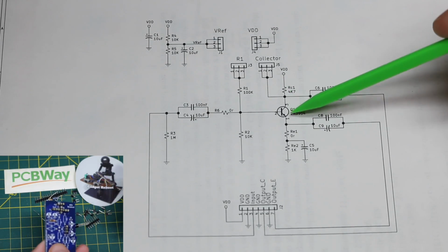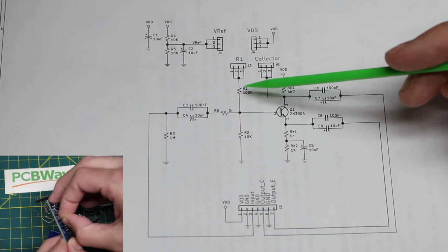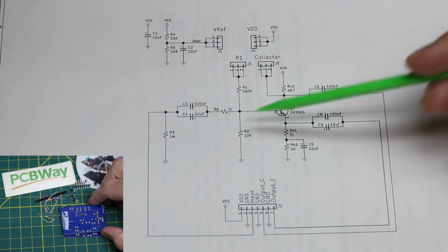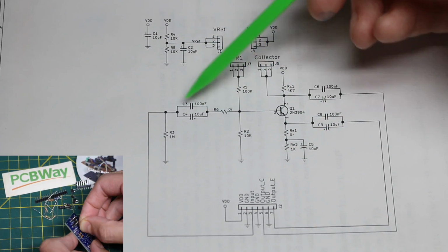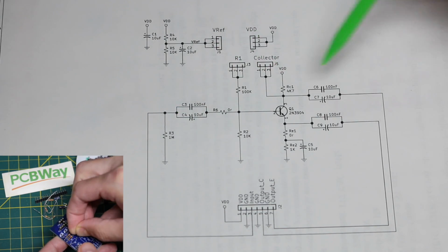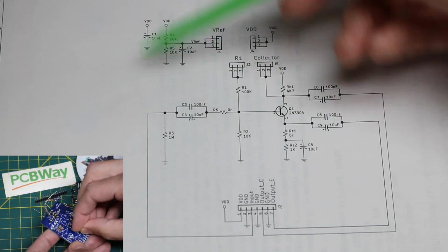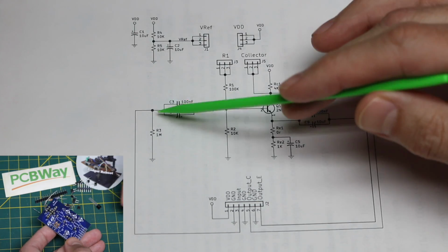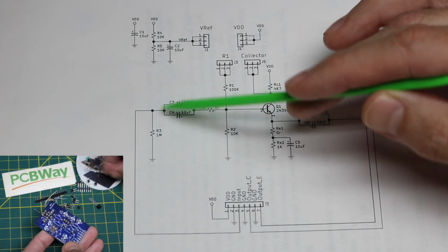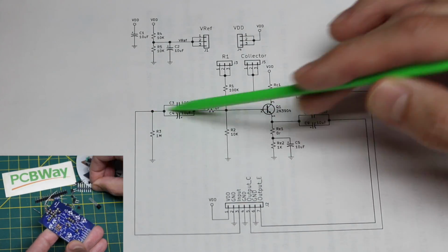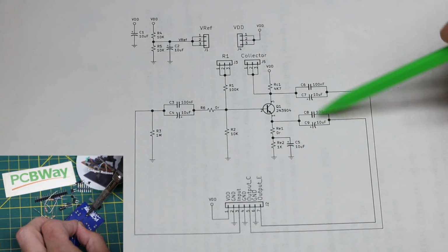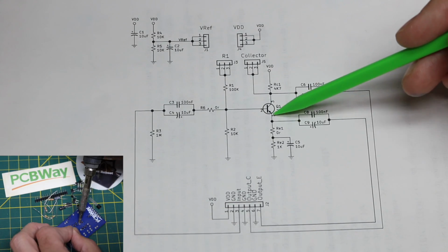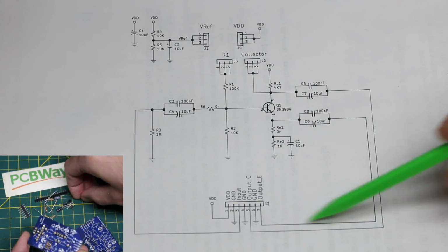So I have an NPN transistor, I have resistors for a voltage divider bias, an emitter resistor, and a collector resistor, space for capacitors for input and output, and then there's other optional components. I can put a 1 meg resistor to ground on the input to give the input capacitor a ground reference. I can also set this up with an output off of the emitter if I want, and I have a header pin for that.